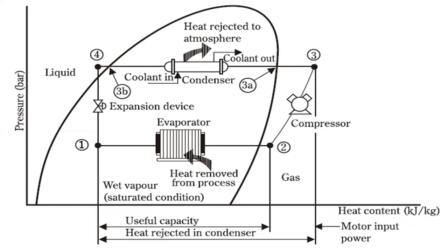A further reduction in temperature happens in the pipework and liquid receiver, 3B to 4A, so that the refrigerant liquid is subcooled as it enters the expansion device. Then the last stage, from 4 to 1, the high pressure subcooled liquid passes through the expansion device, which both reduces its pressure and controls the flow into the evaporator.